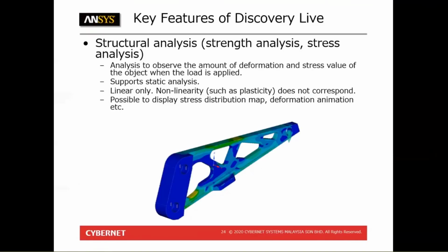So, continuing with the key features of Discovery Live. First, we have structural analysis, or some might call it strength analysis or stress analysis. This analysis is to observe the amount of deformation and stress value of the object when a load is applied to it. In Discovery Live, it only supports static analysis for now, and also only linear analysis.